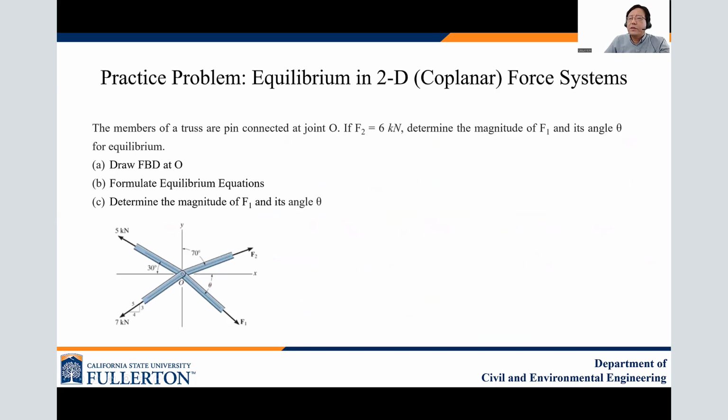This slide shows the practice problem. At first, you need to draw a free body diagram at O. Then you need to formulate the equilibrium equations. And using the equilibrium equations, you can determine the magnitude of F1 and its angle theta.